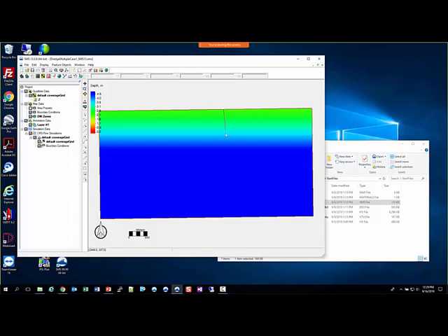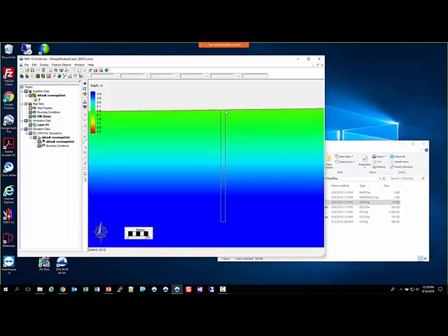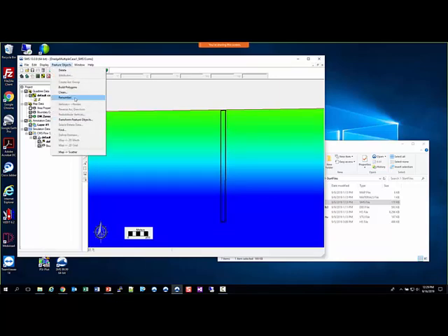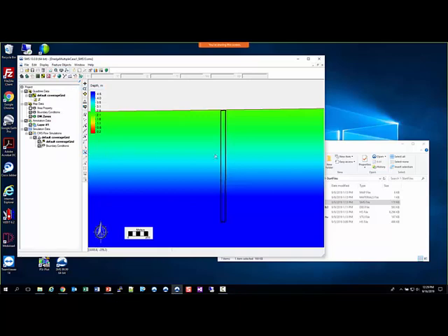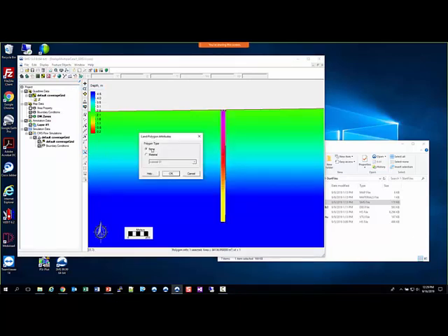And so what we're going to do is just say, okay, I want to dredge a channel from here to here, and it's going to look something like this. And then I make sure I close that back on itself, and then I can go under Feature Objects and Build Polygons. And then once that's there, I can double click on that and make sure that it is an enclosed polygon. We don't have to do anything as far as materials or anything like that right now. This is just going to be used to select the cells inside of this zone for editing later.